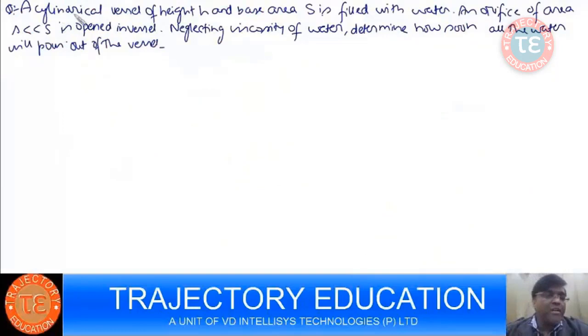See this question. A cylindrical vessel of height h and base area capital S is filled with water. An orifice of area small s, very small compared to S, is opened in the vessel. Neglecting viscosity, determine how soon the water will pour out of the vessel.